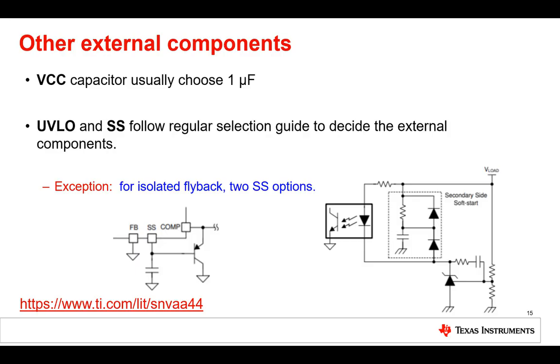Please keep in mind that ceramic caps have DC bias. DC bias means that the capacitance reduces with applied DC voltage. So please use a ceramic capacitor that has a low DC bias. Normally, bigger packages and higher voltage rating means less DC bias.